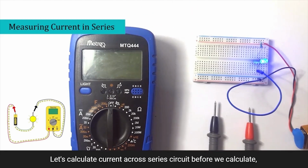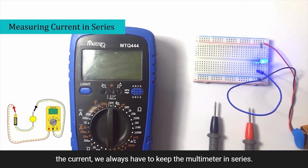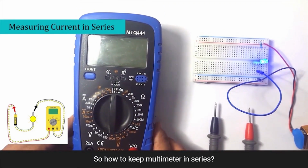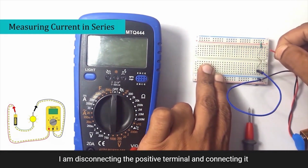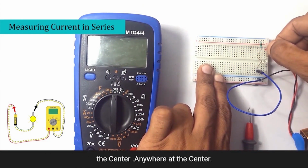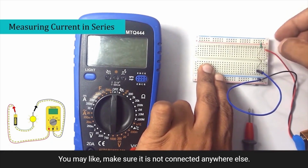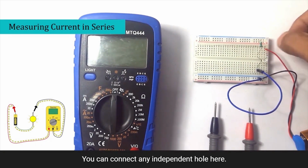Now let's calculate current across the series circuit. Before we calculate, we have to first understand that whenever we want to measure the current, we always have to keep the multimeter in series. So how to keep the multimeter in series? As you can see, this is a closed loop. I am disconnecting the positive terminal and connecting it at the center. Anywhere at the center you may like. Make sure it is not connected anywhere else. It should not short to any other terminals. You can connect it to any independent hole here.